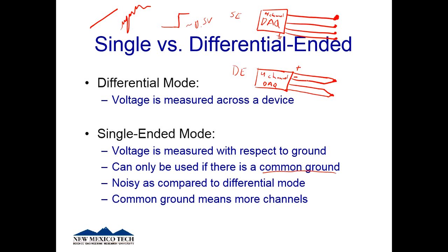And so you can actually subtract, so the noise you're picking up, the other electrical interference and such, is partially getting canceled out because you've got 2 wires and one of them is positive and one of them is negative. So that same noise is getting canceled out. There are some other techniques, and we'll talk about that a little more next week.